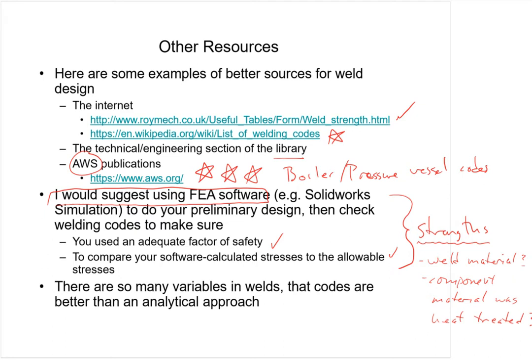So the actual strength of the material you're welding, in the vicinity of the weld, could be unknown. And that's why, in general, when you get down to the final weld, there are so many variables. This is important here. There are so many variables and unknowns, and that's really why they've developed codes. The codes are basically developed from actually welding a bunch of stuff and ripping it apart, then repeating the process, getting a statistical set of data, and going on like that.